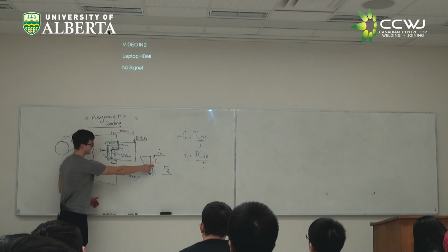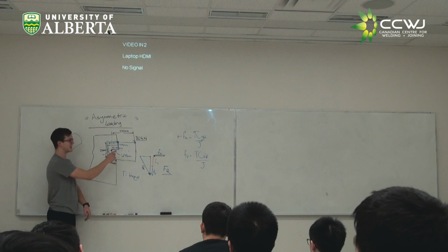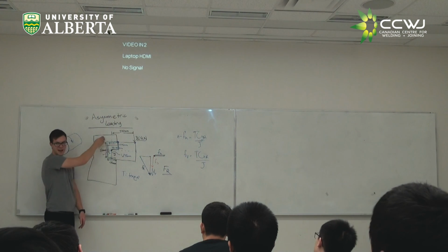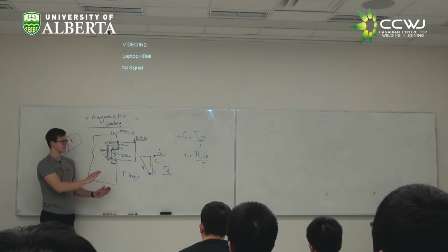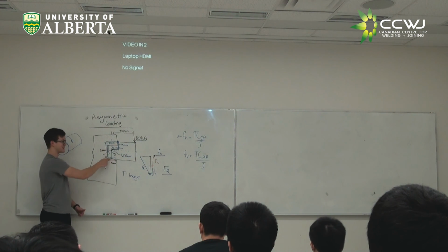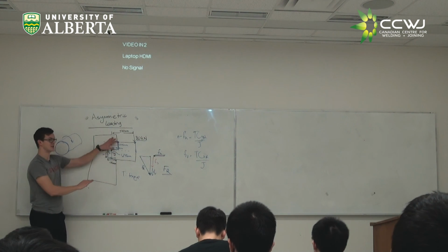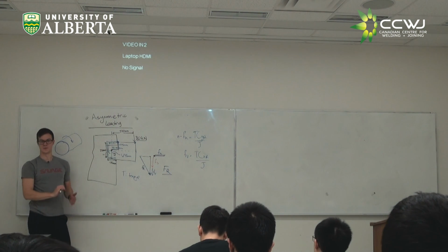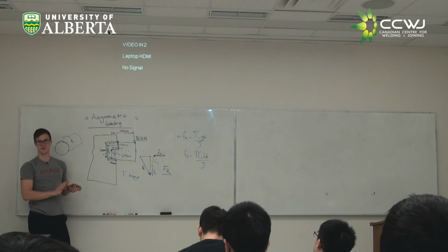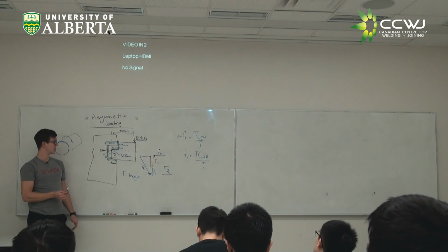We still have to solve for this FS, but that is exactly the same as what we did for the last situation. That is assuming this 80 kilonewtons passes through the center of gravity. That's basically the whole previous problem gets wrapped up into that FS part, but we're not going to worry about corrections for the angle in that case. So we could just say FS is 80 kilonewtons?